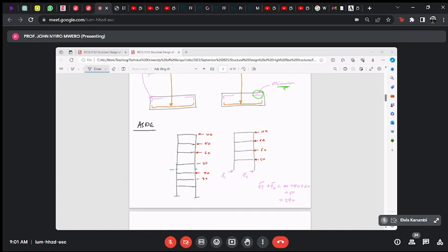We said if we have a column and we just elongate it so that we achieve a bigger stiffness in a certain direction. So being a column, it is supporting some part of the slab, so the slab will load onto it. So you need to check for that. But you find that the axial load that goes onto the shear wall, because it's such a large, almost linear element, is usually not the governing factor for the design of the shear wall. What would cause the shear wall to fail would actually be the bending moments. That's why we've talked about the bending moments.